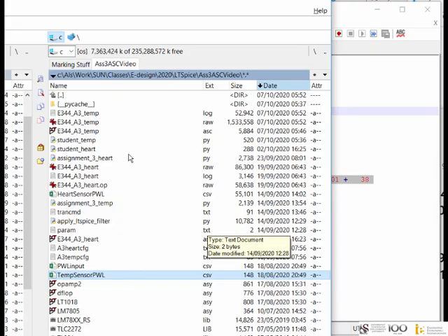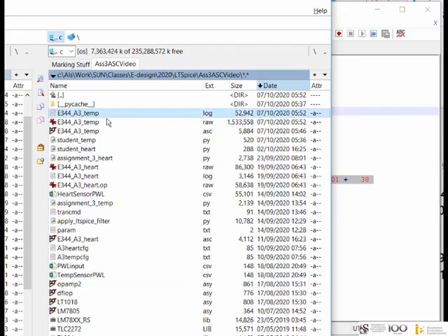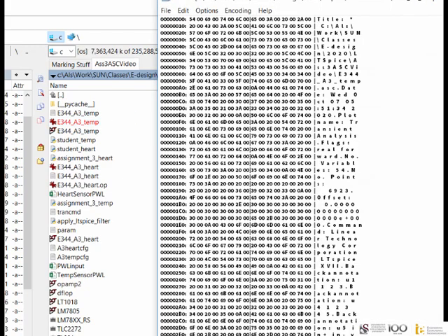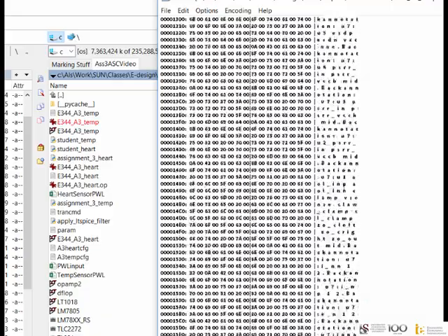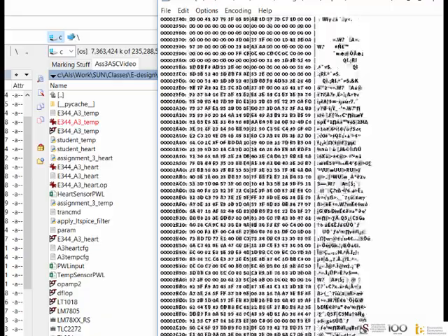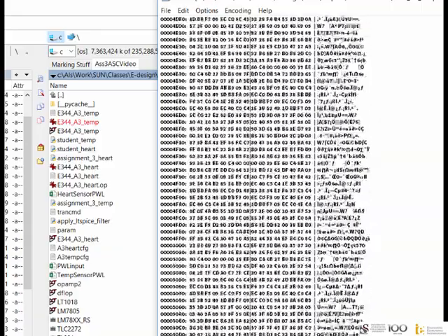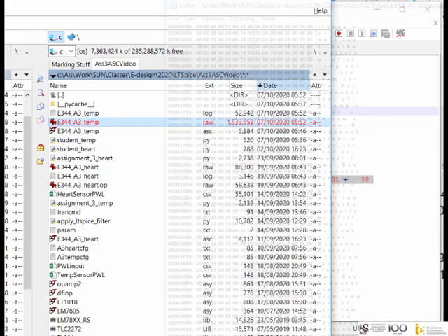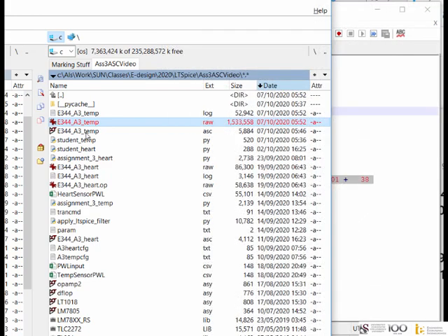So now I'm back here, and now considering that simulation generated a few things. I don't know if you realize this, but this raw file that I'm indicating here, this is the output. If I go and look at this, it is the actual output. There's a bit of a header there, and then it's the raw dump of my data. There we go. That's the raw dump of the data. The first bit is preamble, and this is essentially what the Python is intercepting to check with the output of your circuit. But it's going to generate that for itself.